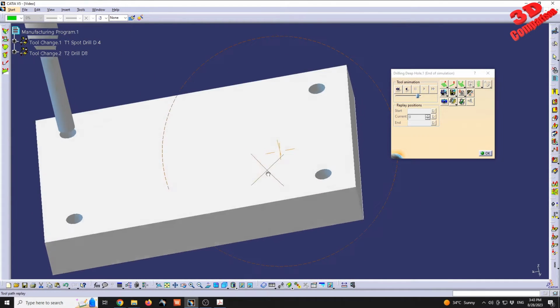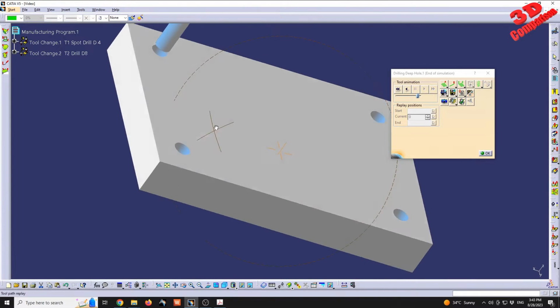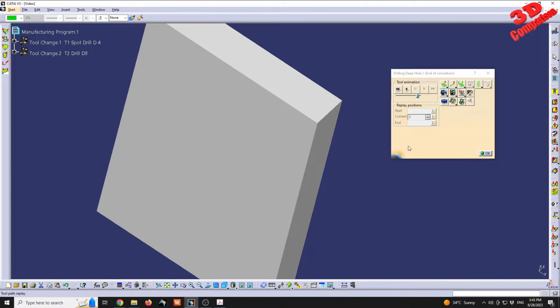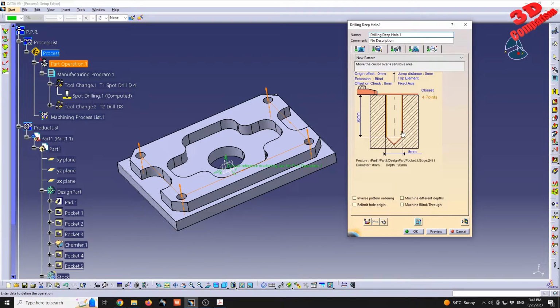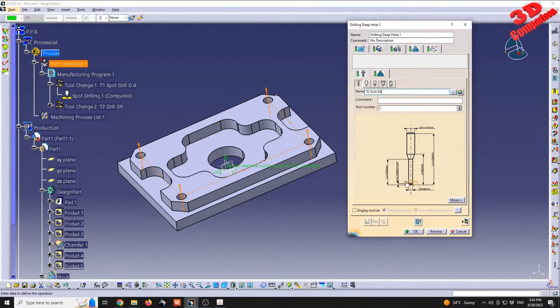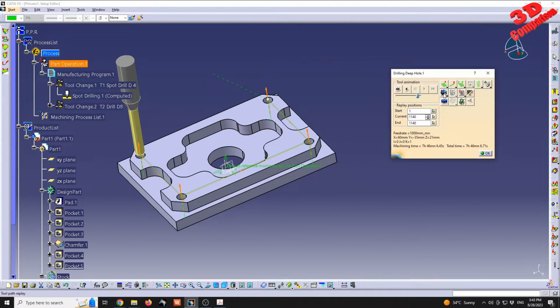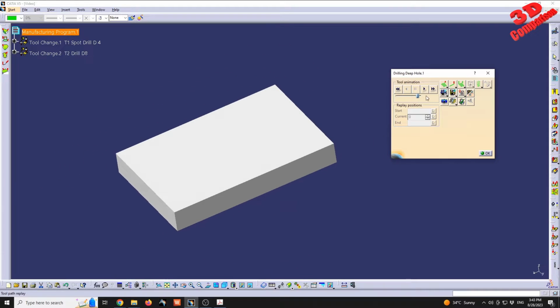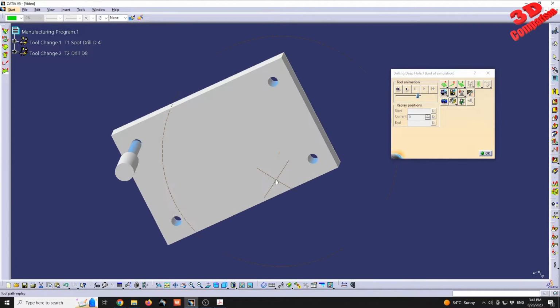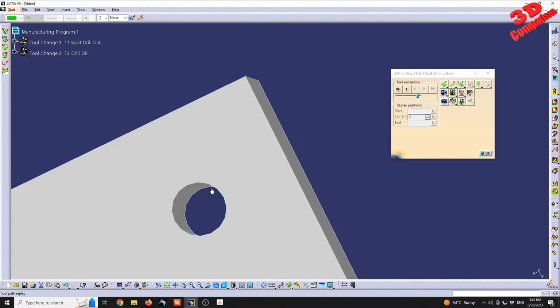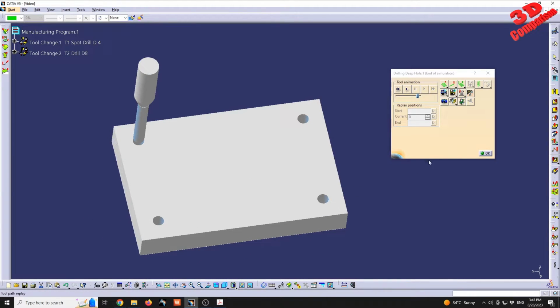But we see visually that now the drill will not pass to the other side, therefore we need to adjust the hole depth. So I will go with more, like 24 in this case. We see that the drill has this hole, so we cannot adjust the end. We can only adjust the diameter. But like this, we're going to see that we're going to have that pass through.